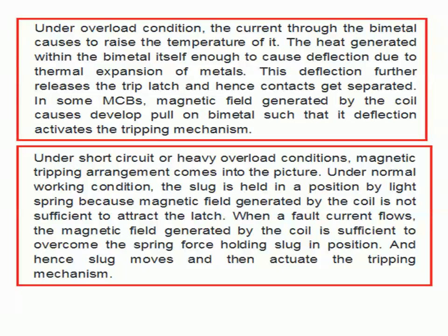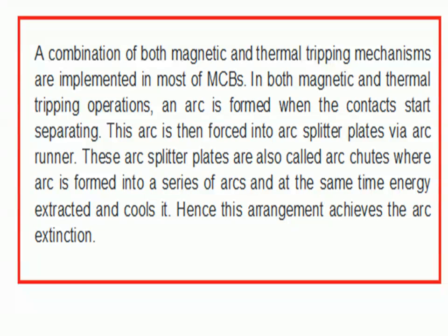Hence, it also opens the moving contact from the fixed contact. Hence, both are designed in MCB. A combination of both magnetic and thermal tripping mechanisms is implemented in MCB designs. So both operations are useful.